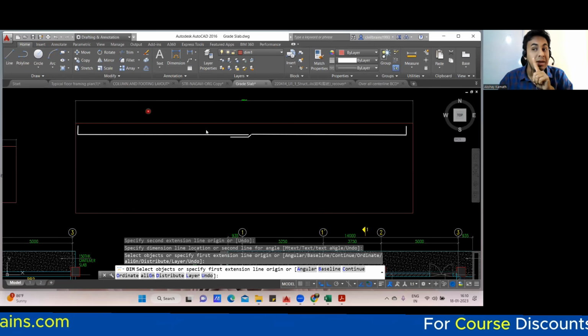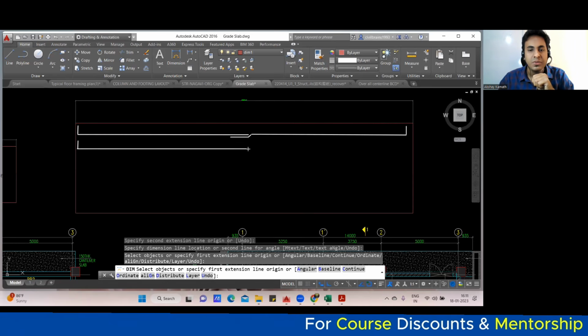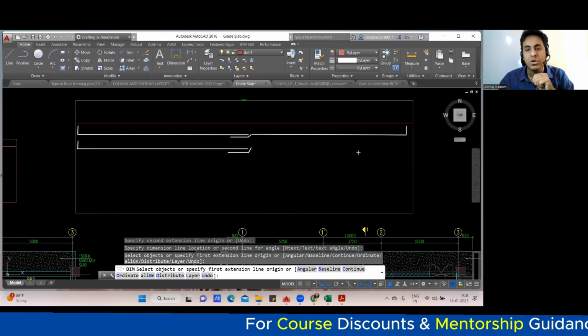Now, you know that every time a lap is coming, the next bar which you are going to provide, you'll not place it like this again. You'll bring the L-shaped bar. You'll bring it here. Then again, you'll give a lap. Then you give this thing. And you won't take it like this.